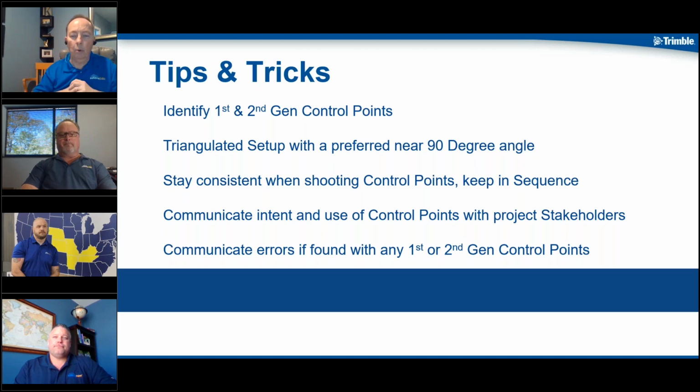Communicate your intent. I think it's a really good point that we want to hit on. Communication is so important on that job site. I've gone to a lot of job sites and I hear this group, maybe it's the mechanical guys, are using their own control points that they've set up. The general's using these control points. It's so important as the general to lay the law down on that job. When you're having your update meetings, we need to establish control on that job. We need to make sure everybody's using the right control, what is designated.